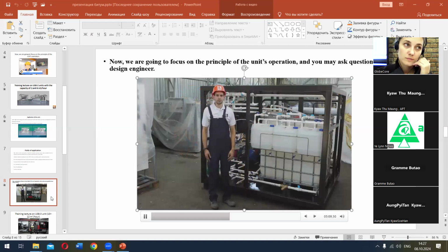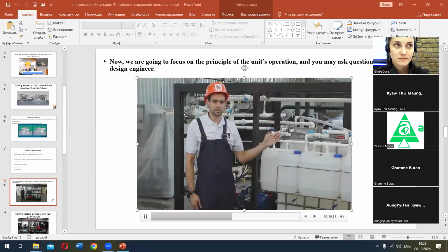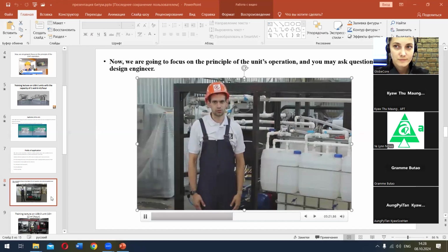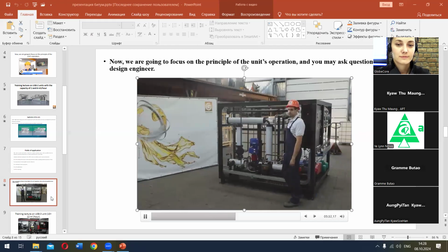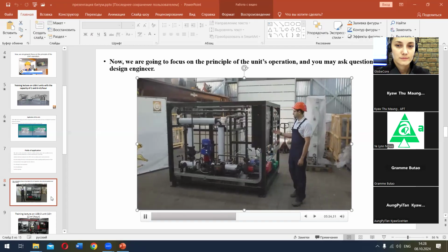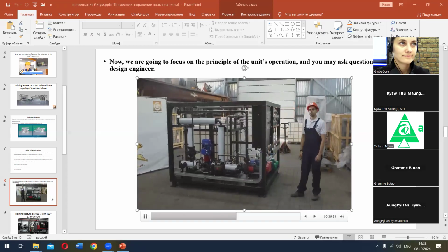Opening the valves of consumption exits allows us to feed our liquids, that is adhesion additive, acid, and emulsifier, into the blend. Liquid circulates for 30 minutes. This ensures high quality mixing of the blend. When the temperature on station T2 reaches 140 degrees Celsius, the operator selects the auto mode and sets the operating modes with or without a thinner, with or without latex.